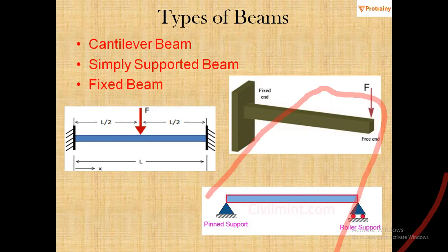अभी when we are talking about RCC, जब हम reinforced concrete की बात करते हैं, it is very hard to find a simply supported beam in an RCC frame, ठीक है ना, because जो casting होती है beam की, slab की, वो monolithic होती है. RCC में it is monolithic. जब वो casting monolithic होती है तो there is always going to be a certain amount of fixity. तो इसका मतलब ये है कि purely simply supported beam होना is not possible.